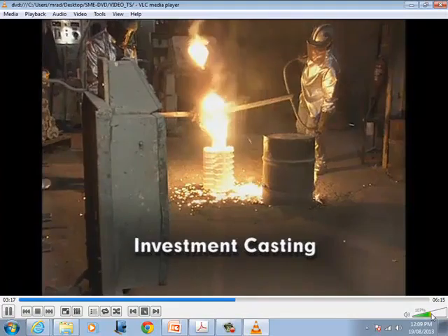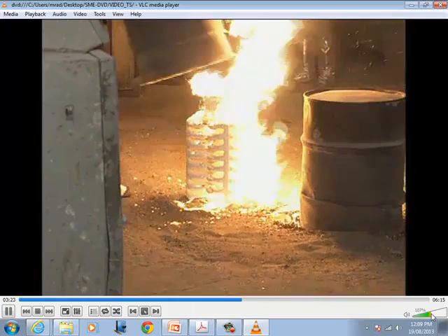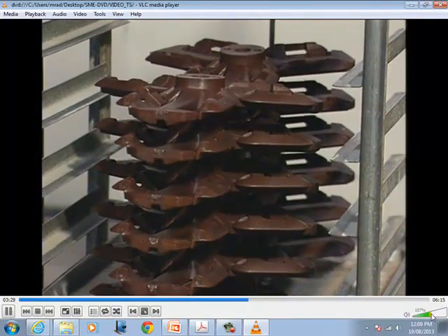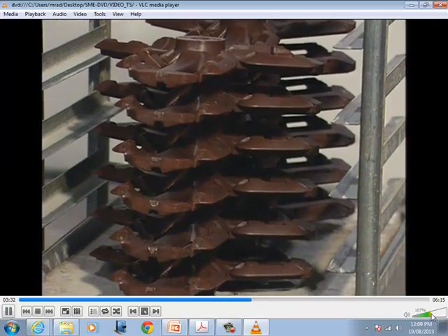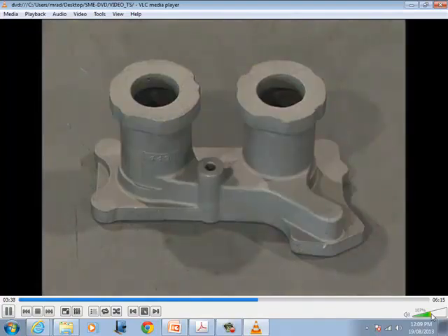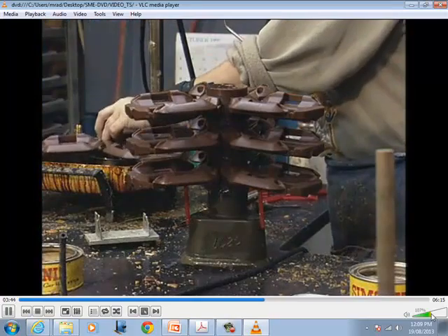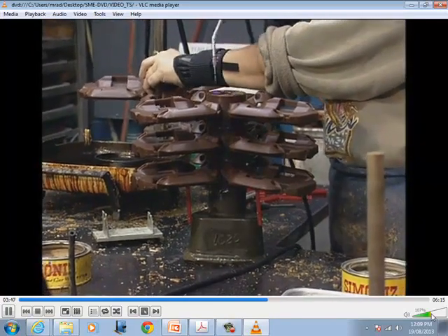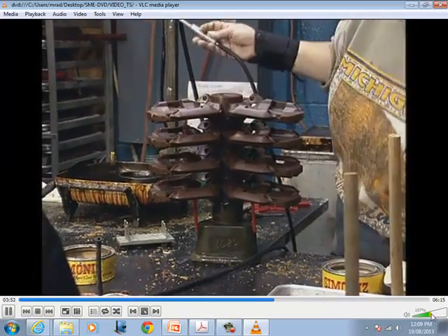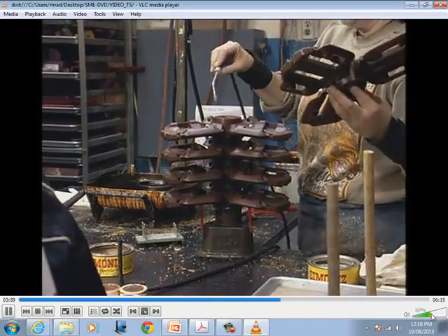Investment casting is a precision process using primarily ceramic shell molds. Investment casting is also known as the lost wax process because wax, a principal pattern material, is consumed during the mold-making process. Consumable plastic patterns are also used. Investment casting patterns are made by injection molding. These patterns are assembled onto a wax post connected to a pouring cup. This pattern assembly, called a tree, usually incorporates complex runner systems to assist metal flow in the investment casting process.